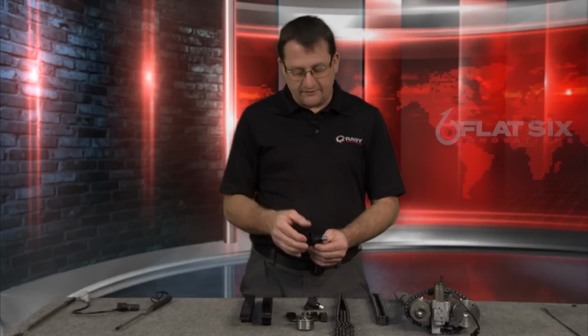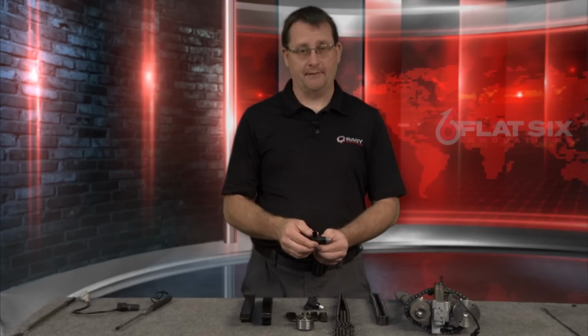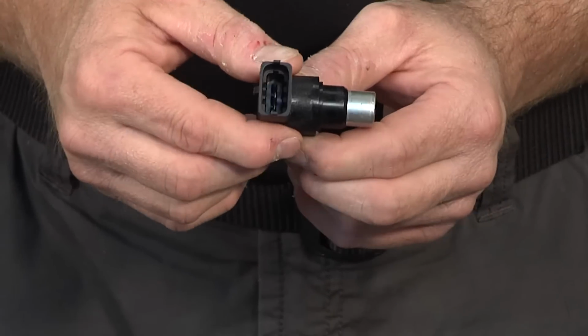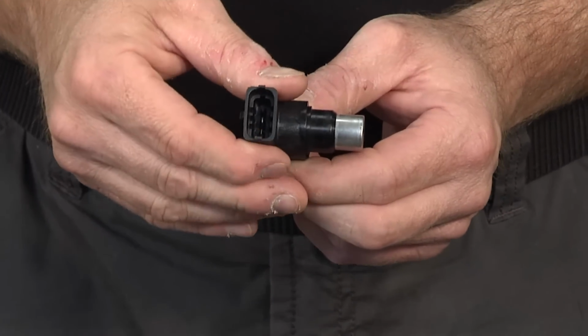So that being said, when people start getting a diagnostic trouble code for a camshaft sensor out of range, the first thing they want to do is change the sensor. I'm with you on that a little bit because, hey, let's just throw the parts cannon at it, right? The diagnostic code came up and said something about a sensor. But pay close attention to what it says about the sensor.